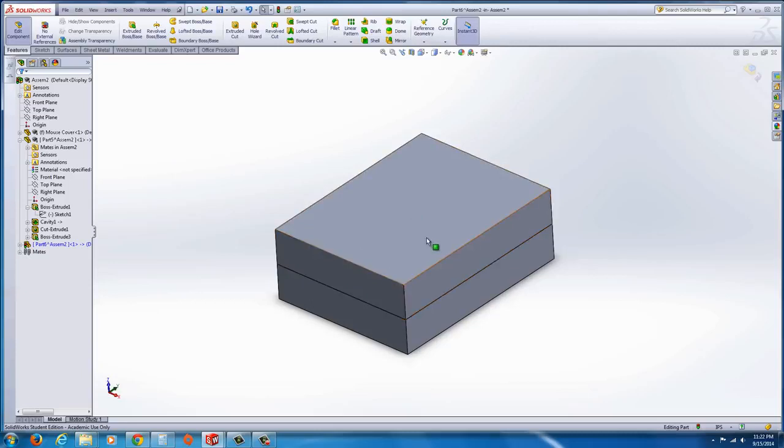And now I want to subtract these 2 parts from this. Again, just mimicking what we did in exercise 2. So it's really nothing particularly new. In this case, though, we did have to separate some open holes. If you remember in exercise 2, actually in exercise 1, we prepped the part where we removed all the holes, so it was very easy to split the cavity in the core.